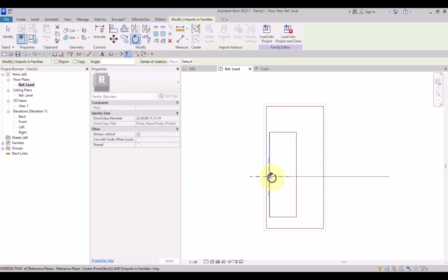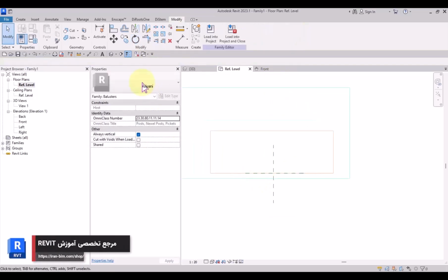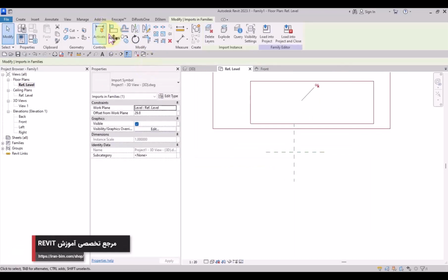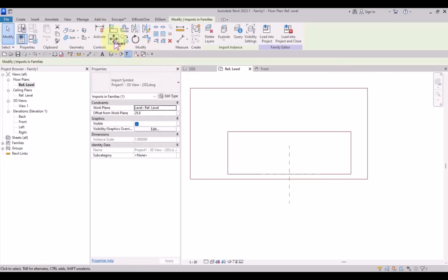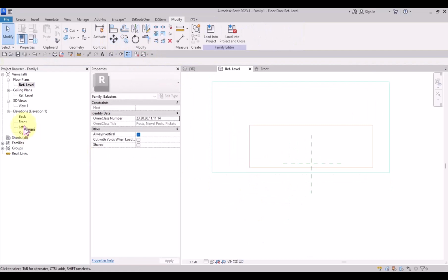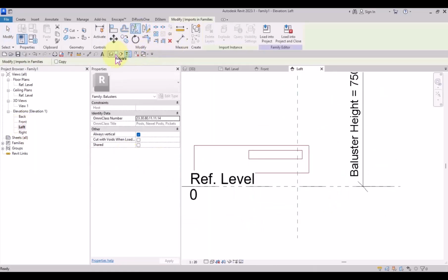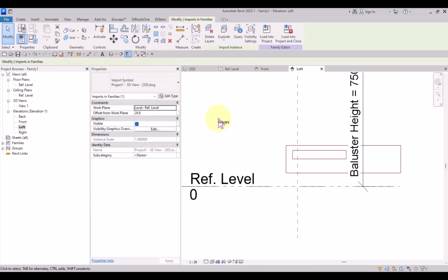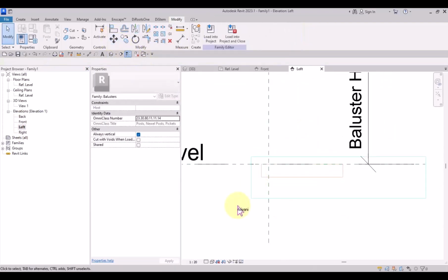I rotate it 90 degrees, and again select and with move here to here, and because of 3 centimeters nosing, push forward as 30, and I shift it to the left view, and now mirror, and then we use copy and we make it symmetric, and I make a move to here. In fact, this part is the thickness of the cap.